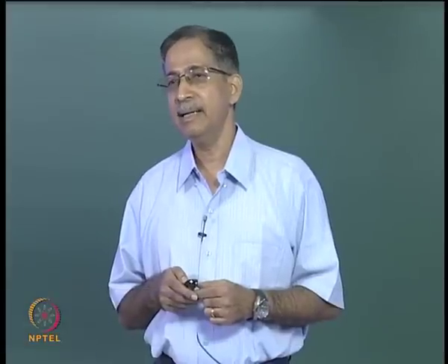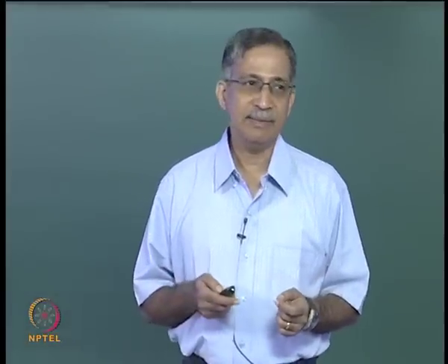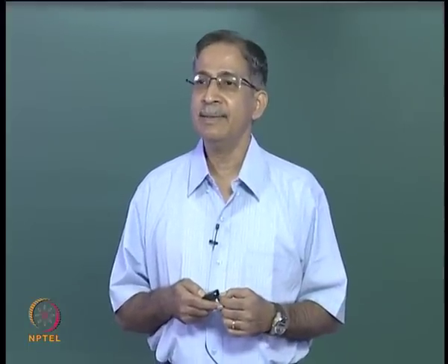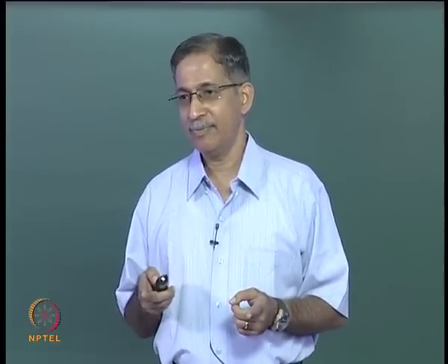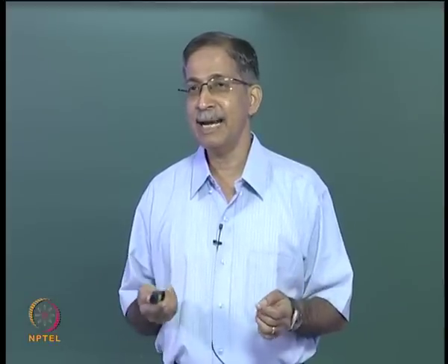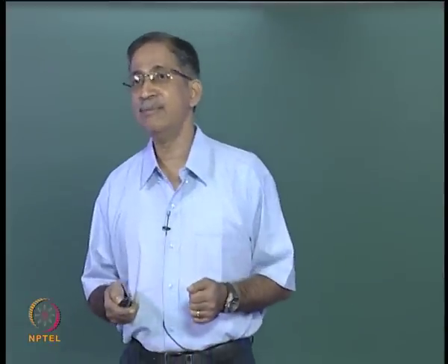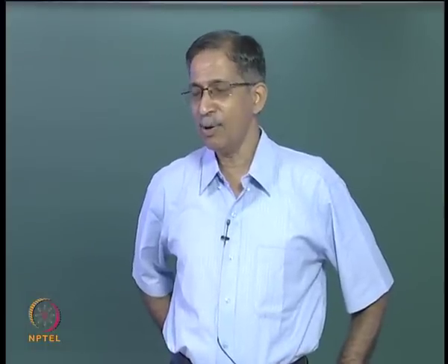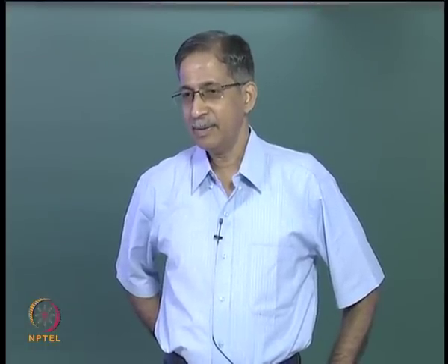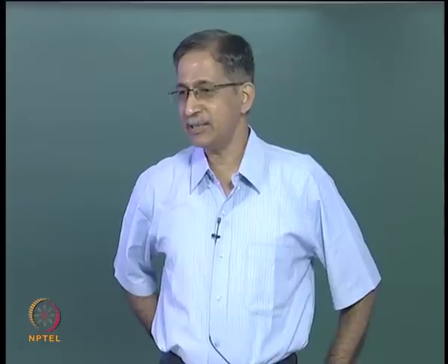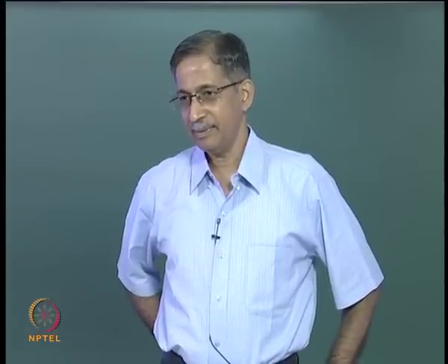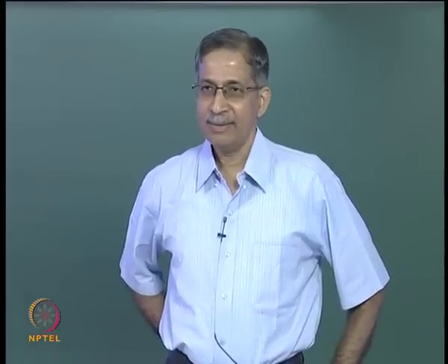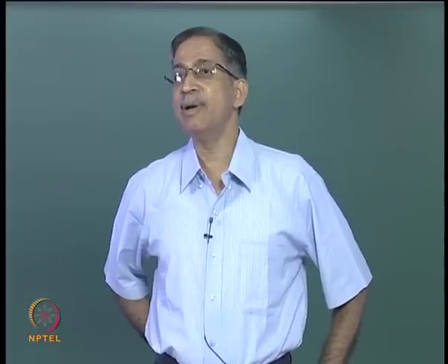Here you have 4 degrees of freedom. We have looked at this element earlier. Now this is a prismatic beam element. Length is Li in the ith element. Flexural rigidity is constant EI. Can you write down, from first principles, from the physical approach, the 4 by 4 element stiffness matrix for this element? I will show you how this can be derived in many ways, but you already know the answers. You can try drawing the 4 sketches. Just write down that 4 by 4 element stiffness matrix for the sign convention we are following here.